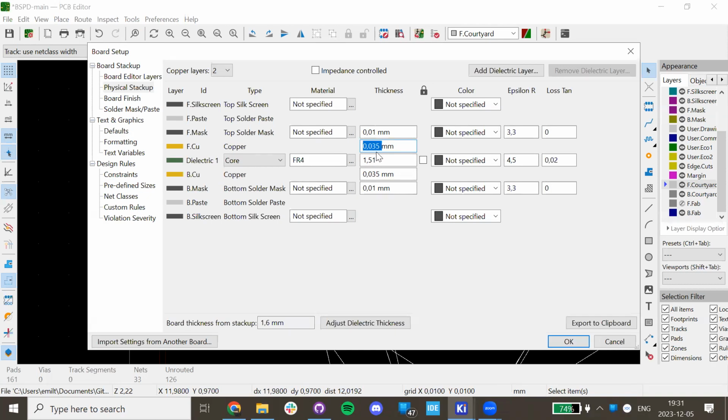I think the thickness is set by what you choose when you manufacture it, but this is good for someone looking at your PCB because you may have dimensioned your traces for a certain copper thickness. So if you reorder the PCB and haven't changed this, and it should have been a 2 ounce board and you ordered it as a 1 ounce board, it can burn out. So important to check.